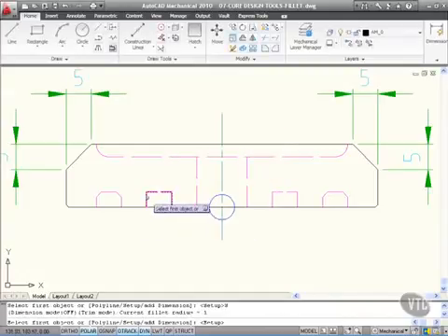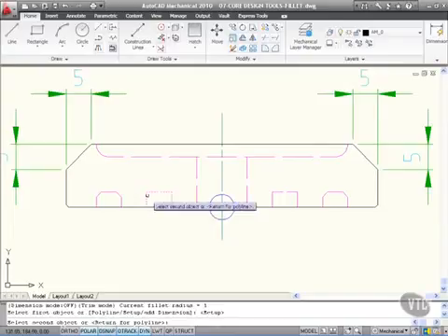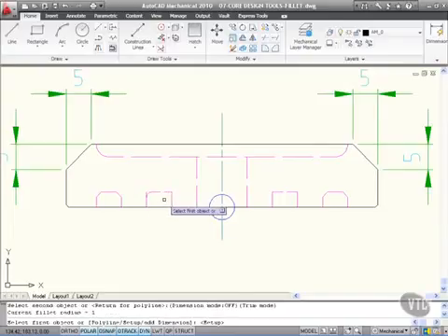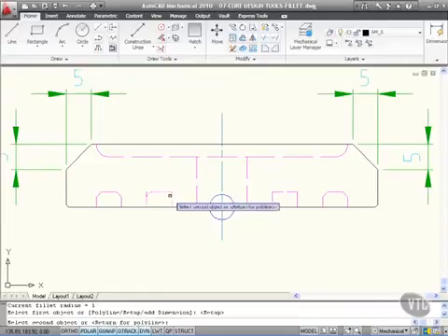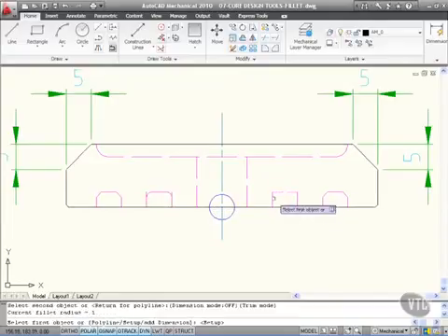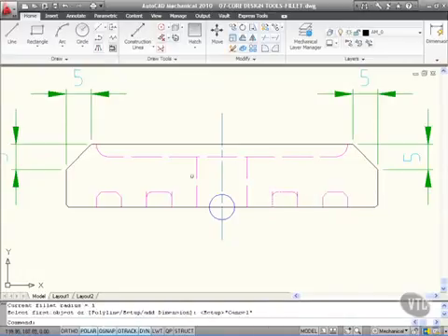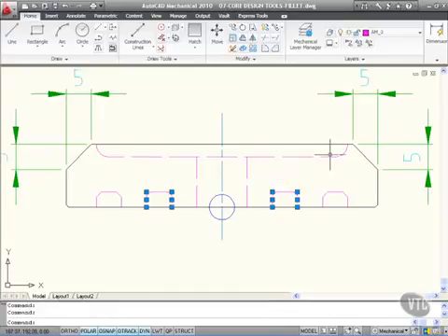I'm going to work on these grooves here. So I select that line there, that line there. Notice there were obviously lines underneath, as before with the chamfer. So I'll just quickly tidy these up, like so, and then remove the lines that I don't need. So again, press escape when you're done. And then it's 1, 2, 3, and 4. Delete those, and there's our filleted grooves in line with our chamfered grooves there. So that ends the exercise on the core design tool of fillet.